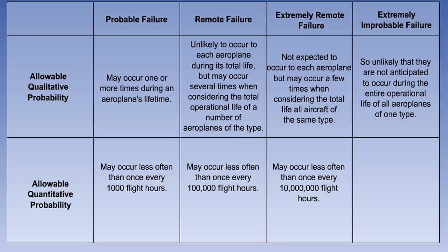Extremely improbable failure conditions are so unlikely that they are not expected to occur during the entire operational life of all aeroplanes of one type, or less often than once every 1,000 million flight hours.